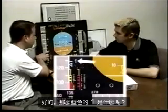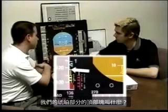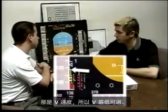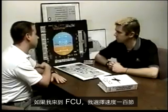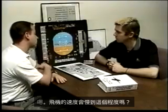Okay, and what would be that blue one? That's V1. The top block of our amber portion is called what? VLS. Okay, and VLS is what? That's V is speed, so V lowest selectable. Okay, if I come up to the FCU and I go select speed 100 knots, will the aircraft slow to that?